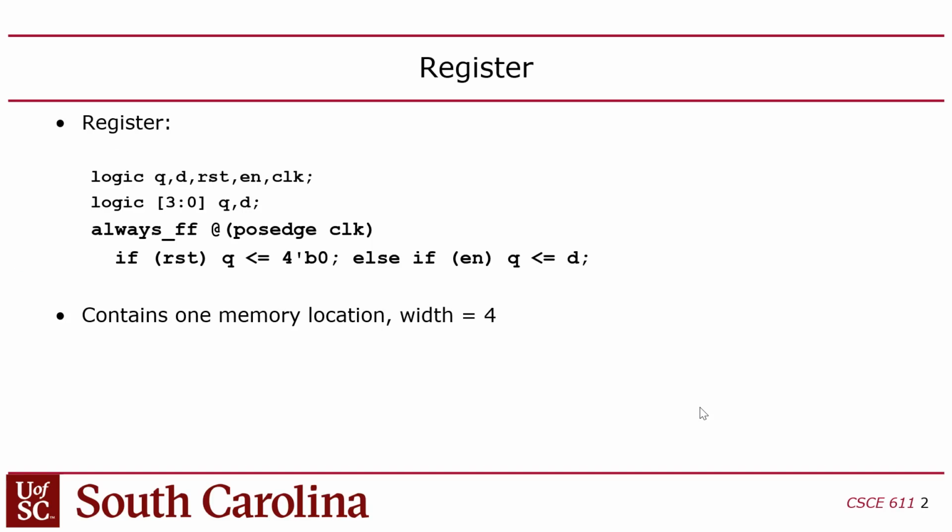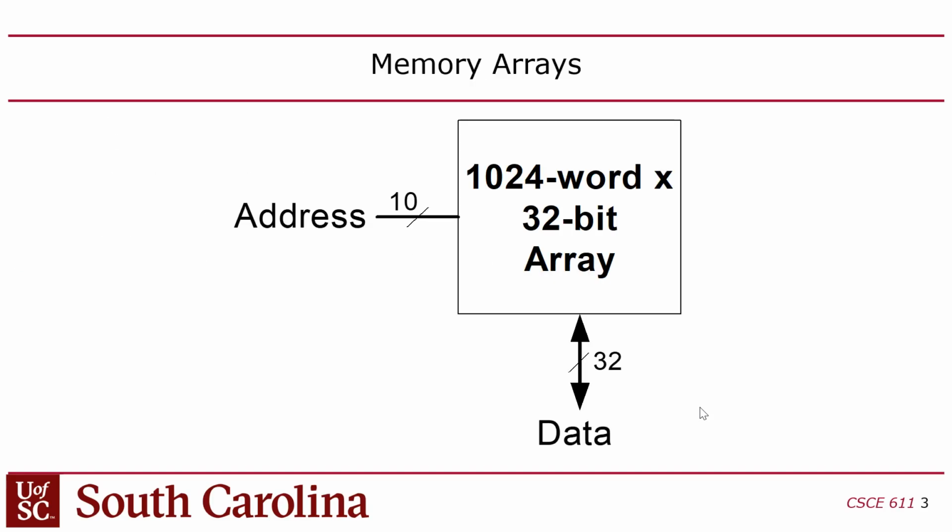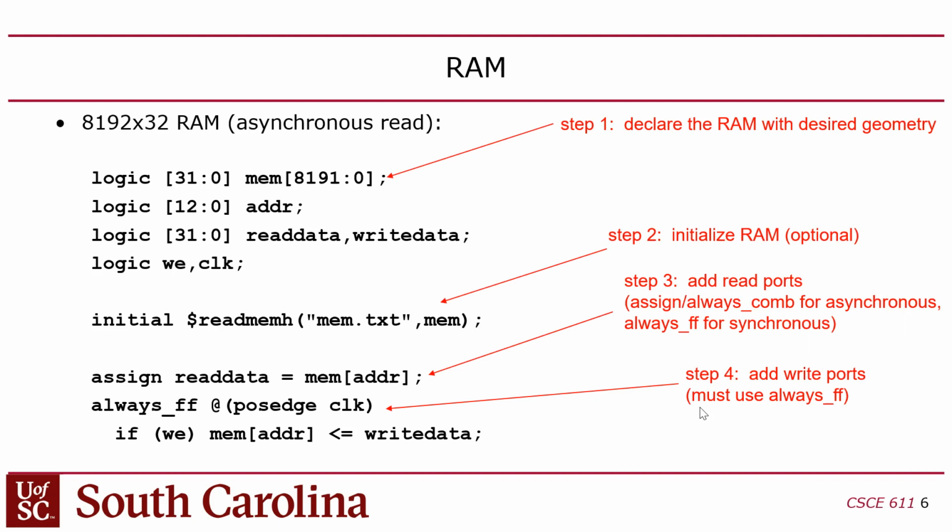So we talked about RISC microarchitecture, and we talked about RAM arrays. And RAM arrays are going to be used for our register file. A RAM array is where you provide an address, and then you can read or write. They are organized as a two-dimensional array of bits where you have a depth, which is the number of entries in the array, and the width, which is how many bits you can access at a time, in one cycle. And then you can have multiple ports on a RAM array. Each port allows you to do one access at a time.